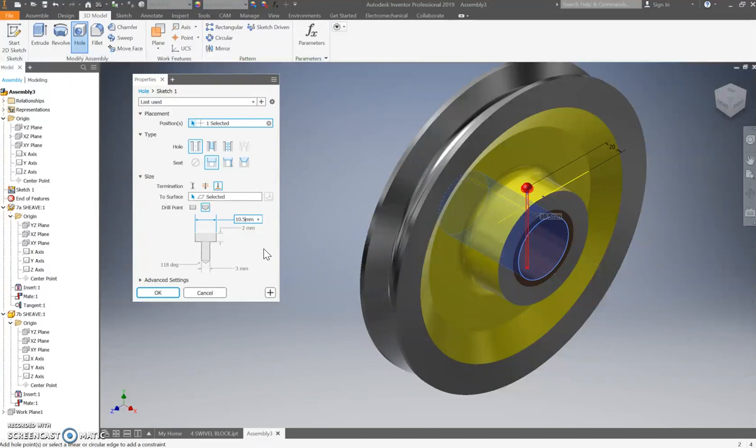And a good rule of thumb, if you're drilling a hole for a metric thread, if you use that 1.5, which is measuring the pitch, and take that away from the original diameter, it's pretty close to the correct tapping size for your hole. So in this case, 12 take away the 1.5 because that's the pitch, gives us 10.5. So let's go with that for the diameter.